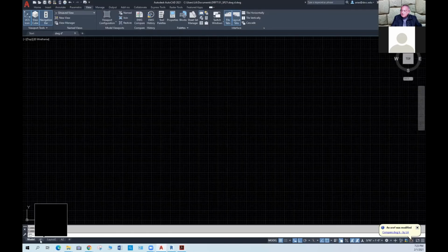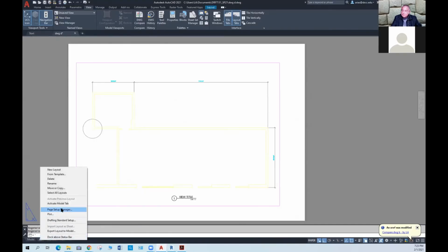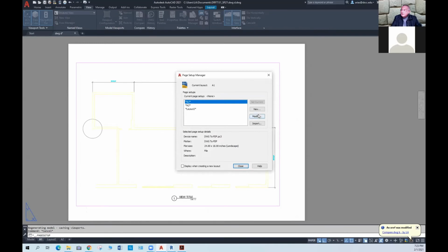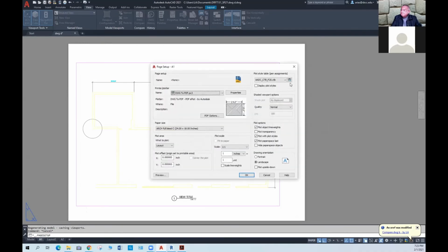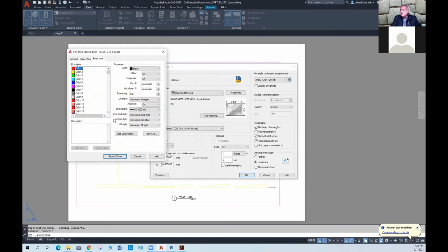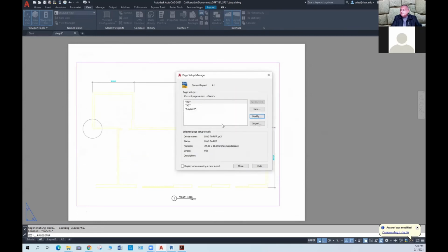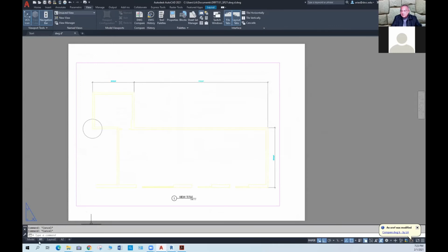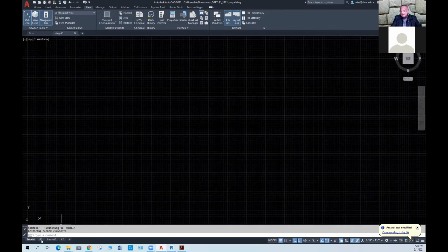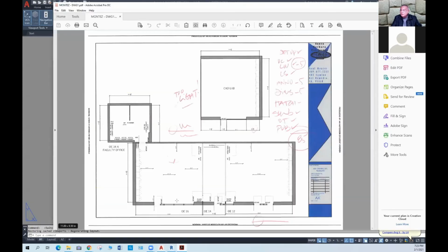You go to the CTB. It didn't show up at all in yours, but it showed up on mine, which is kind of weird. So maybe make it a different color that is going to print better. Typically in the CTB that I use, maybe make it blue or something like that.